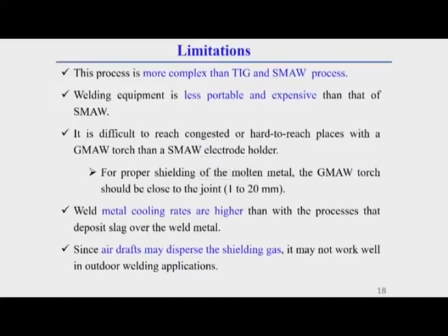Now we will see the drawbacks and limitations of this welding process, because we are comparing it with other welding processes and we should see how advantageous it is and how much limitation there is. This process is more complex than TIG welding or SMAW welding, because there are many control systems like gas as well as water cooling system, as well as current control and feed control. So this is a little more complex than TIG or SMAW welding.